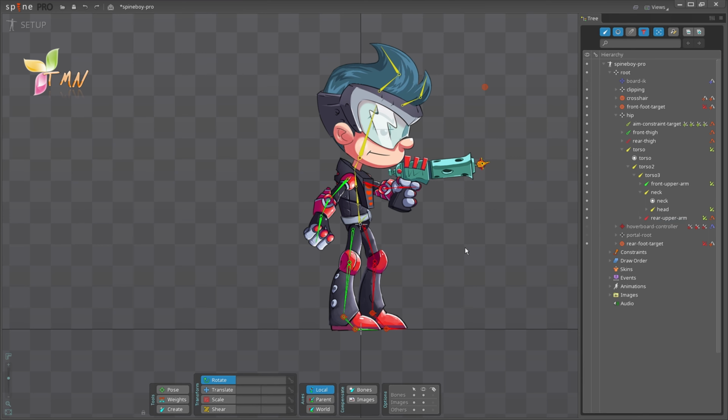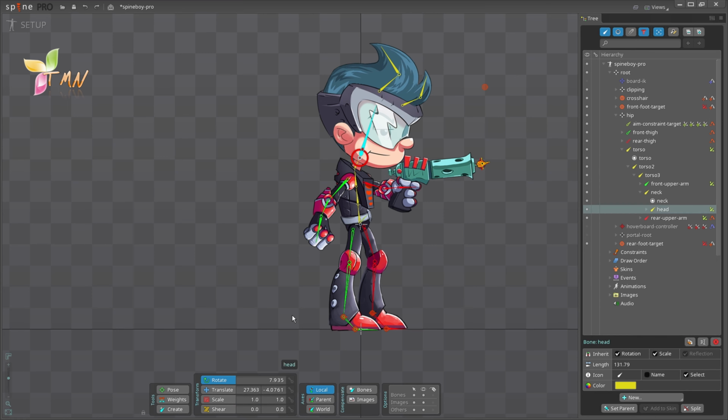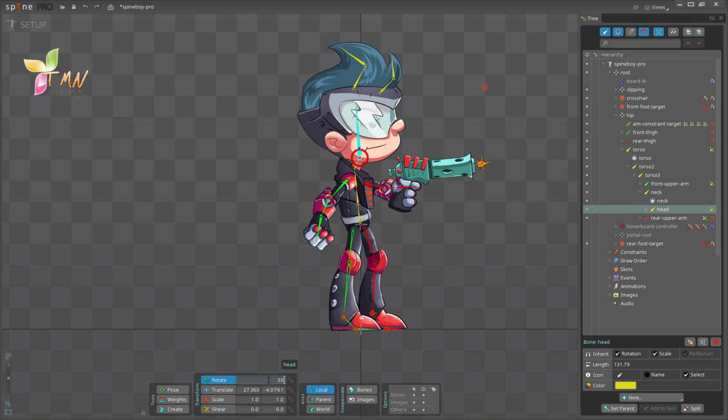Each transform tool has a numeric value which is displayed down here. You see these fields here. And if I select a bone, you can actually see the values. Now if I wanted to change one of these, I could just select the rotation here and enter 30. Then the new value will take effect once I hit either Tab or Enter. So here, I hit Enter and you see it now changed the value, and it displays up here in the editor view.